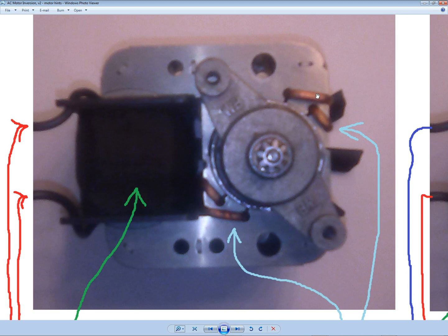But the starter coils are a Tesla invention, and they are induced because the bobbin here of thin voltage, this voltage coil, sets up a magnetic flow in the toroidal stack of laminates, and then that sets up a current flow in these very stout wires.